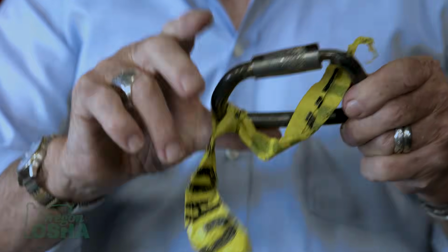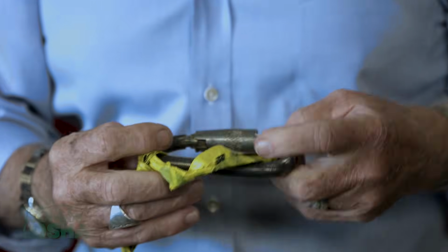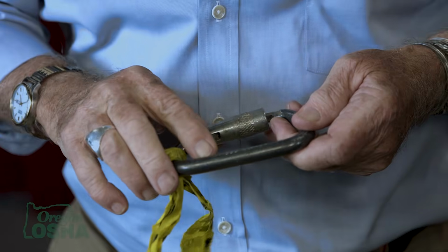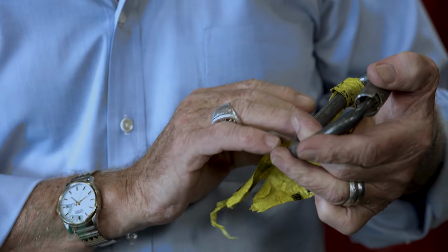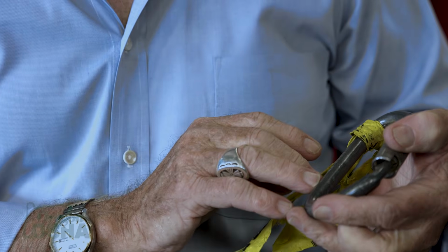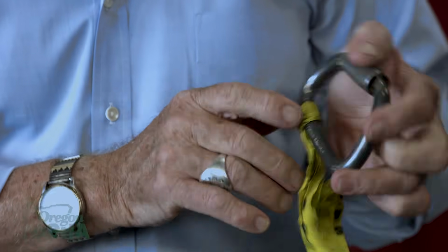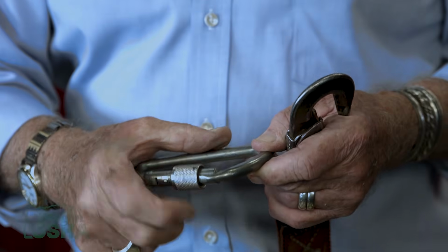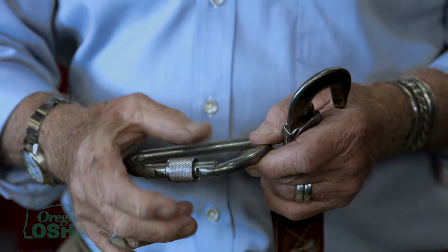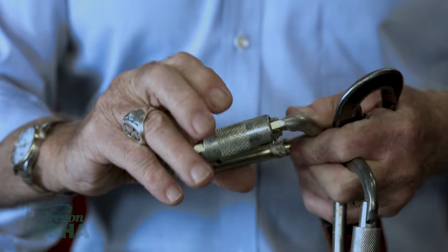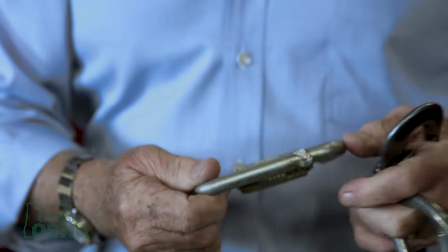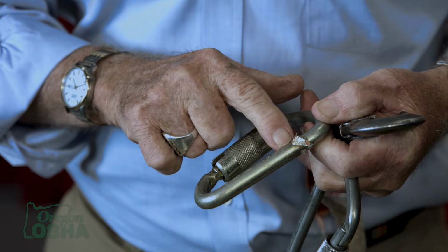Check your carabiners, need to open and close. Read what's on them. Make sure that you understand what's being talked about. It's talking right here about kilonewtons, and it takes 22.2 kilonewtons to be 5,000 pounds. Legitimate carabiner, it requires two separate actions. You look for a fall protection program, something that opens and closes automatically, not something you have to screw shut. But you check them to make sure they close. You read the labels and make sure they're rated.